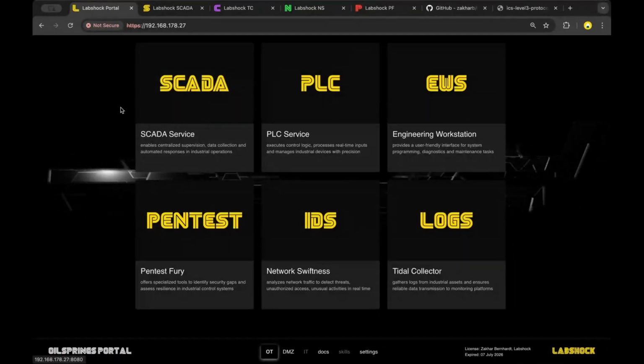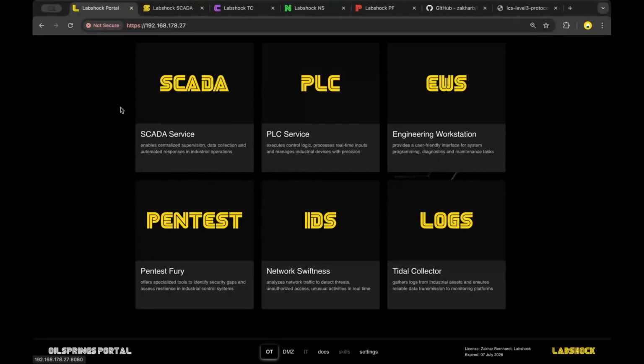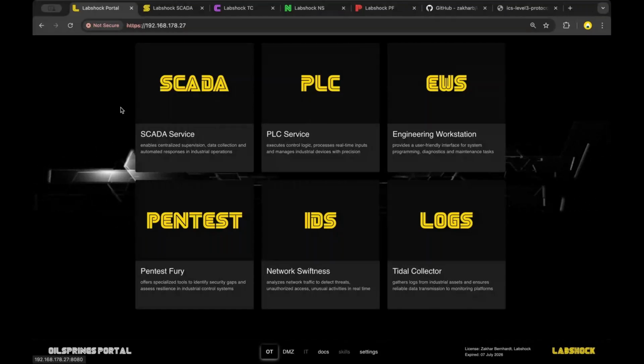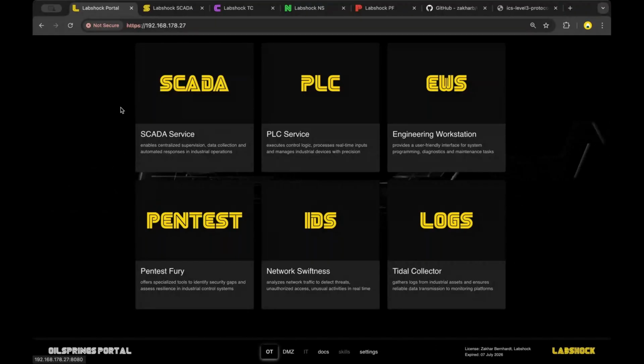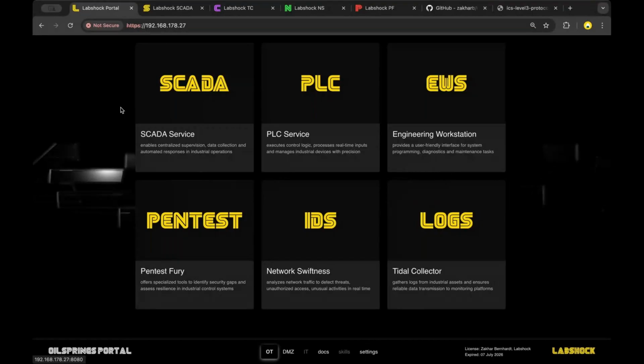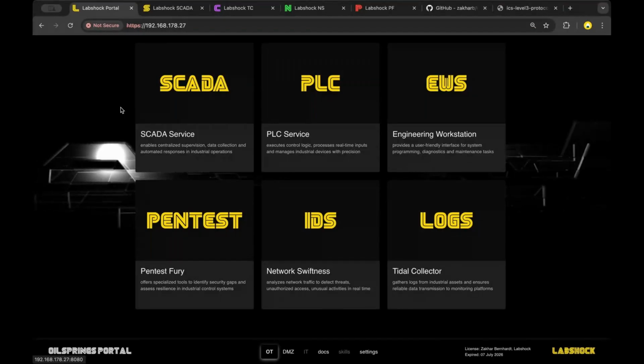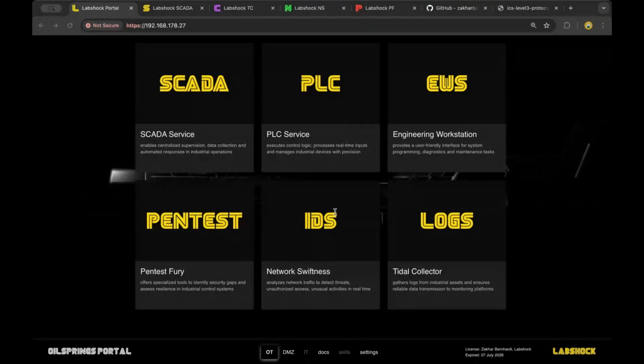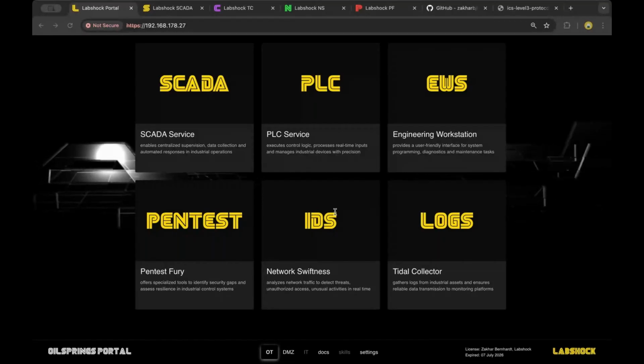Yeah, that's all I wanted to show you about Modbus, how to protect it and how to make your networks safer, because you need to understand that if your PLC is running Modbus, it's unprotected, and anything can change your data. Yeah, that's all from my side, and maybe we can run the poll and switch to the questions that we have.